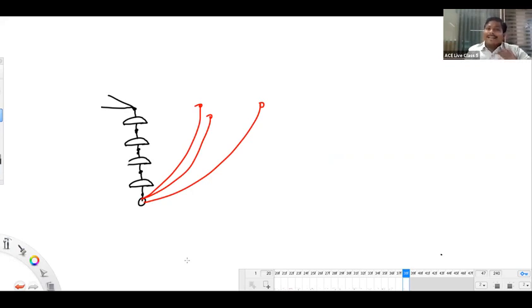Just connecting a wire is not sufficient. We should keep that wire in a proper way. In the sense, we should keep that wire in a proper arrangement with respect to the string in order to cancel the shunt capacitance currents exactly. Who will decide the position of the guard wire in the string?